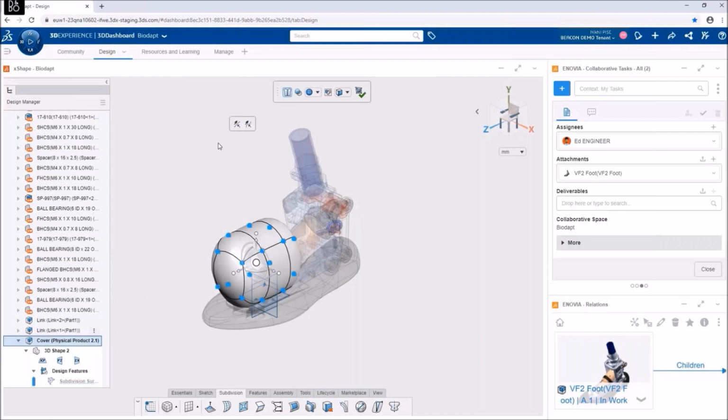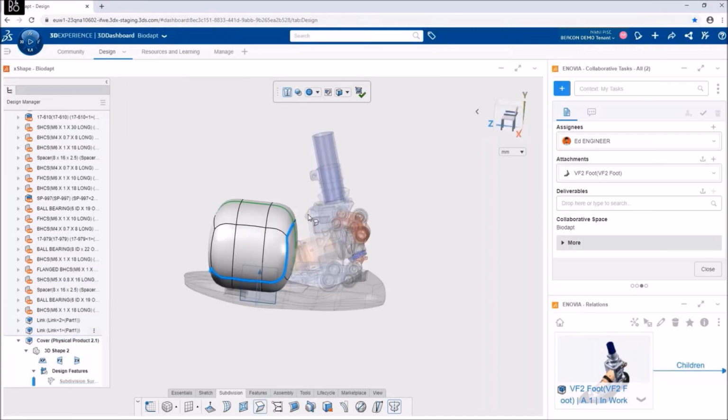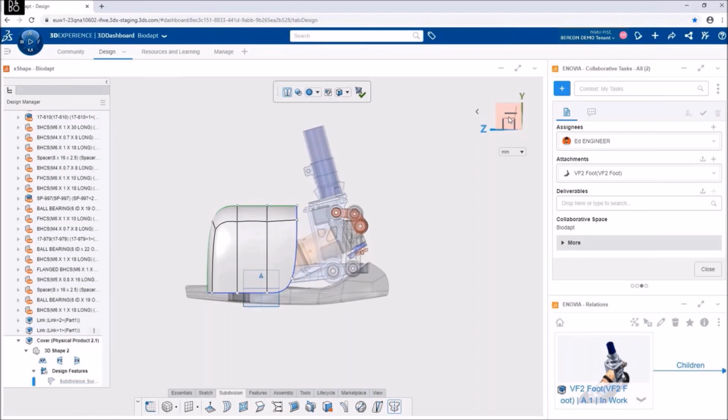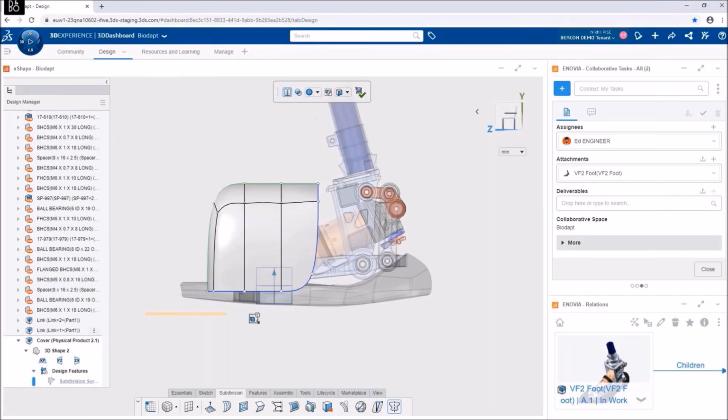You can see there are various points and various edges we can select. First I want to create that component as symmetric, so I'm adding the symmetry. Then I selected some edges and converted them to a flat edge. I'm selecting some points, and with the help of the robot or the handle, I can push the surface from the bottom. And here we have a selection for which direction I want to push or pull that surface or primitive shape. Also we can see a ruler is present, so you can use dimensions as well. Dimension references are there, so you can use them.